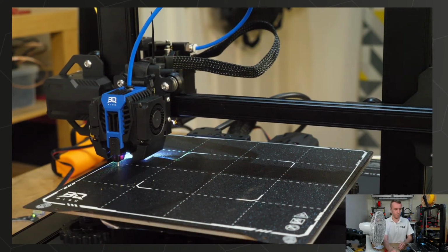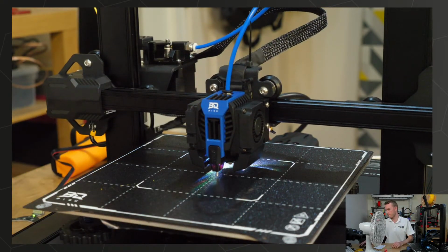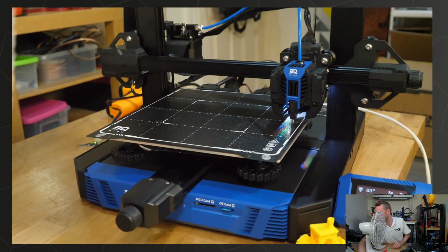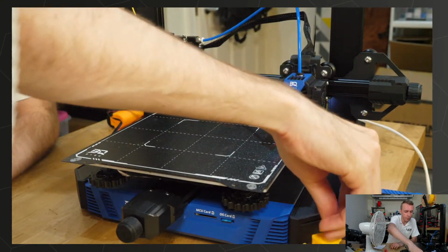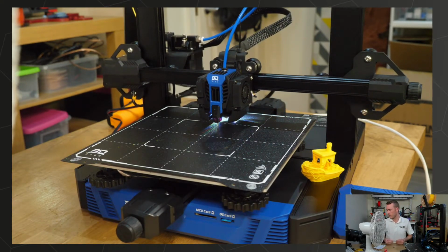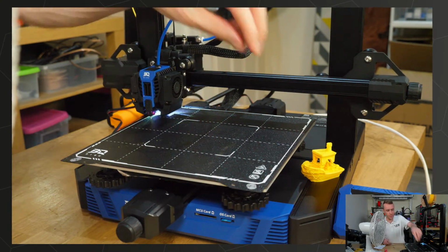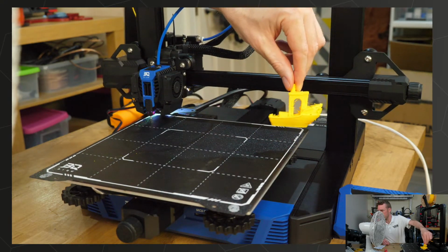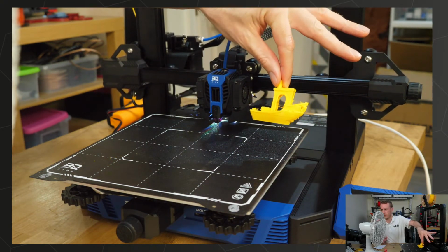Oops. I can't put that anywhere where it's going to stay on the camera. I changed a couple of settings. I changed the bed to spread cycle instead of stealth chop. I can increase the Y motor current. It was always going to be Y that's hitting that limit because it's much heavier. X doesn't look like it skipped a step, which is why it looks really good from this perspective. I mean, it's really good as an exaggeration, okay?